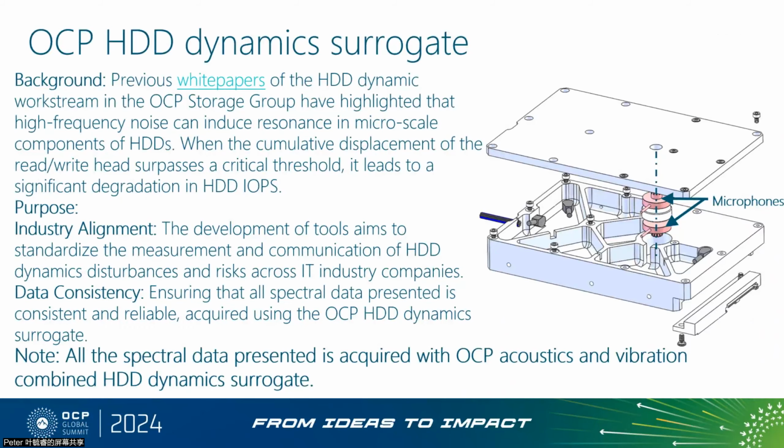Previous white papers of the HDD dynamics workstream in the OCP storage group have highlighted that high-frequency noise can introduce resonance in micro-scale components of HDDs. When the cumulative displacement of the read-write head surpasses a critical threshold, it leads to a significant degradation in HDD IOPS.